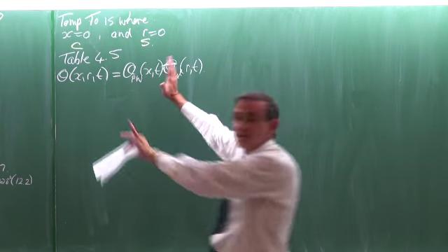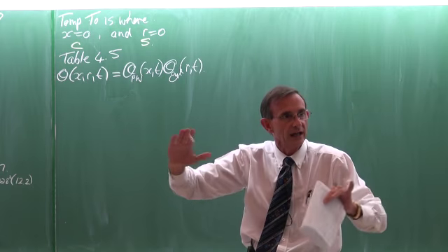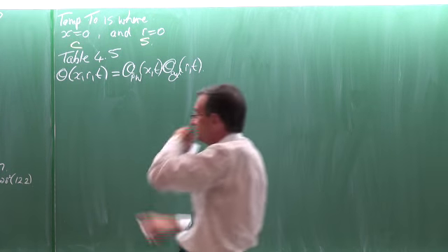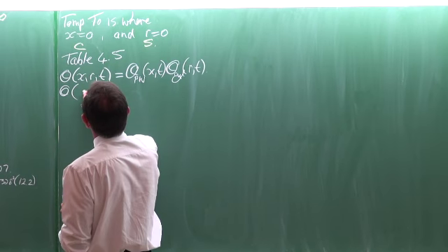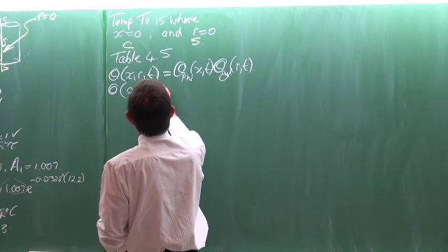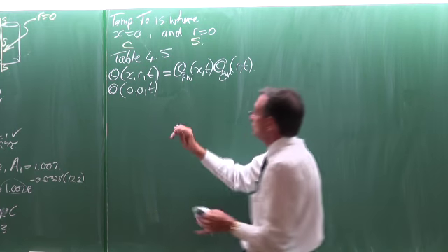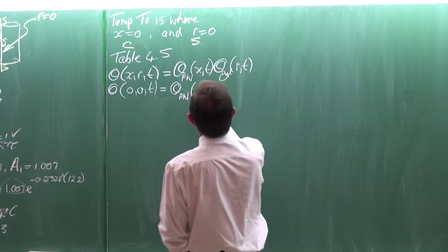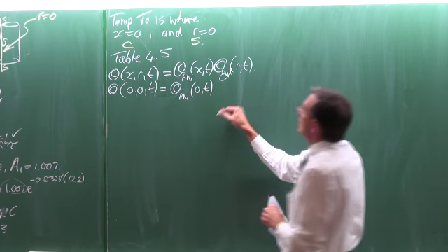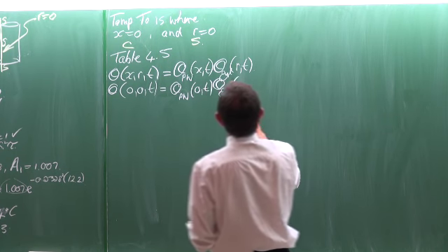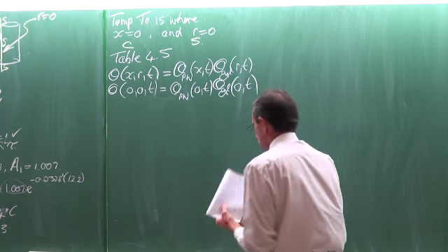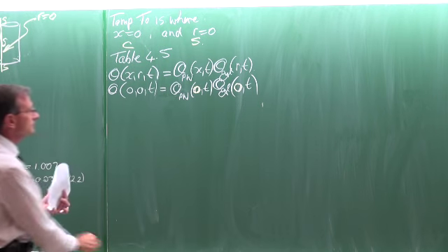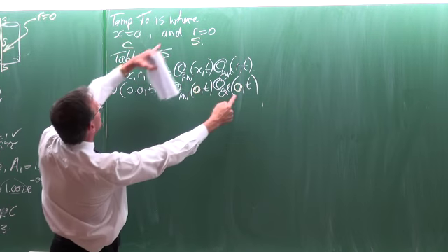So if we look at all the x's and the r's, let's just put it in, because again, we take very, very simple and easy baby steps before we start making things more complicated. So x would be 0, r would be 0, the time is 900 seconds. I'm just going to put in time there for a moment. It's multiplied by the non-dimensionalized temperature for the plane wall at x equals 0, multiplied by the non-dimensionalized temperature for the cylinder, where r is equal to 0. So here we can see the types of solutions that we need: x equals 0 and r equals 0.